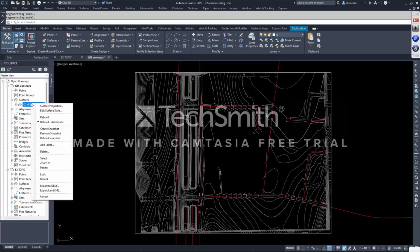If I export out that Land XML design file, you take it and open it up in your total station in the field. And in that design file, let's say I had manholes for sewers, or curb inlets or catch basins, or even a water line like a water valve, or I personally drew in three-dimensional feature lines. Now, I've had this happen, and surveyors love it when I do this. Send them out an XML, they go out in the field, they open it up, and they see not only the surface in the XML, but the points and the feature lines that I created, and they're able to go around to every little spot on that open ground field,